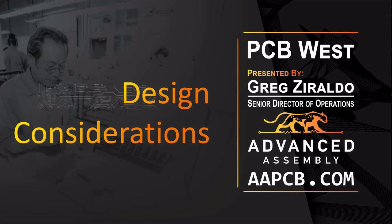Increasing the width consumes valuable circuit board real estate, which leads to fewer boards per panel, which is ultimately going to increase your cost. Increasing the thickness of the traces increases production time a bit, but allows you to put more PCBs on a panel theoretically. The more PCBs per panel results in a lower production cost, and at the end of the day, that means money that you'll save.